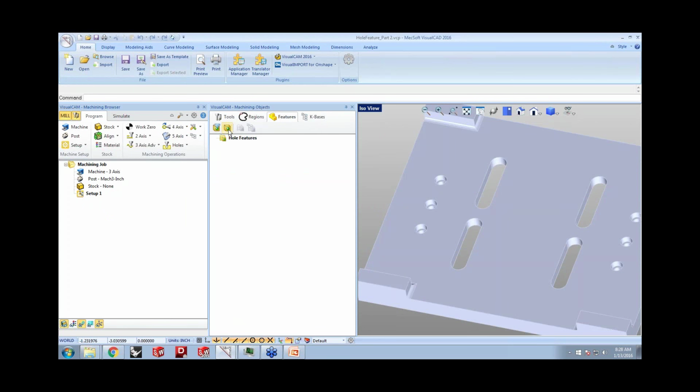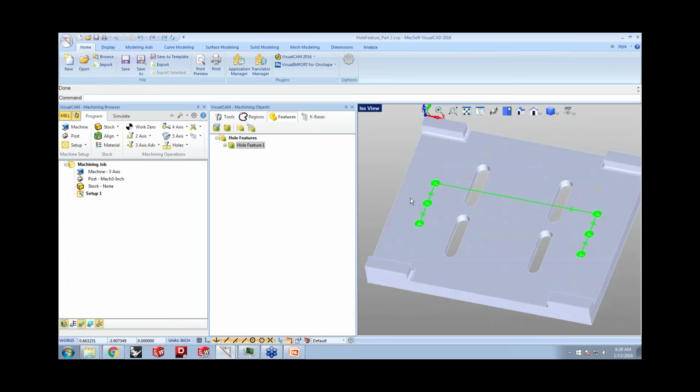So first I'm going to go ahead and identify the hole features from the part by selecting the face on the part. The hole features have been identified, and you'll now notice that there's a feature called Select Matching Knowledge Base and Create Hole Features. So in this process, Visual Mill will automatically go look through your knowledge base of hole features, and if it finds an exact match, it'll automatically go ahead and generate your toolpaths.